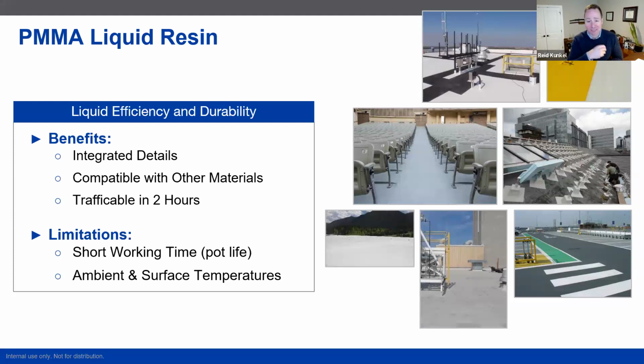It's suitable for a lot of applications, but I would say one drawback, you're looking at a short pot life. It is catalyzed, and so it's got to be applied pretty quickly upon mixing it, which can create some waste if you're not properly judging how much is needed, or how well the conditions are for application.